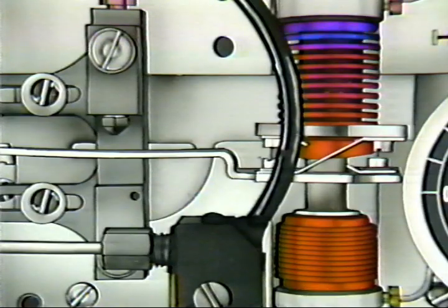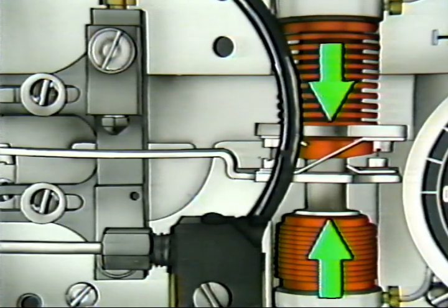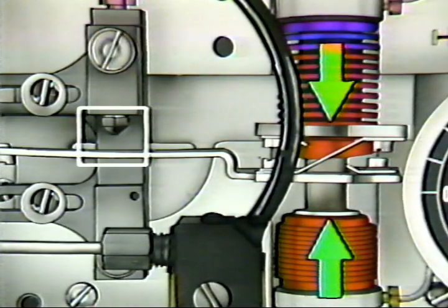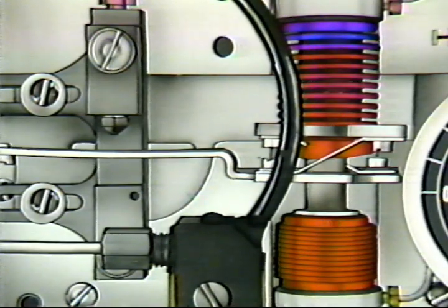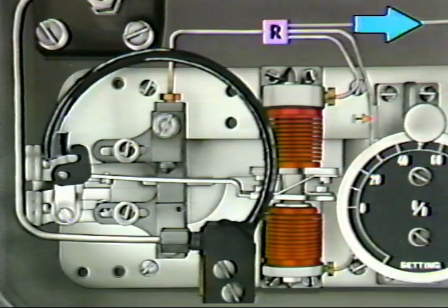As pressure builds up in the reset bellows, the force that it exerts opposes the force of the feedback bellows, which has the effect of holding the beam closer to the nozzle. The output from the controller will continue to increase as long as the process variable is away from set point. This enables the controller to return the process variable to set point to eliminate offset.